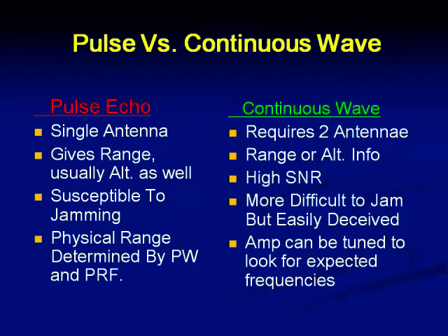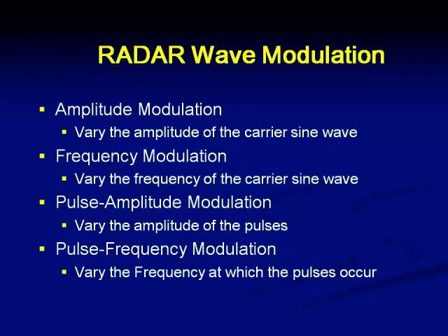That means here there is nothing like a pulse width or pulse repetition frequency, all those things deciding everything in the case of CW radar systems. Now let us see what are the types of modulations we employ. Here normally we go with the amplitude modulation of the sine wave, but in the case of CW radars you need to go for frequency modulation to get the range information. So FM CW radars are used to get the range, otherwise it is not possible also.